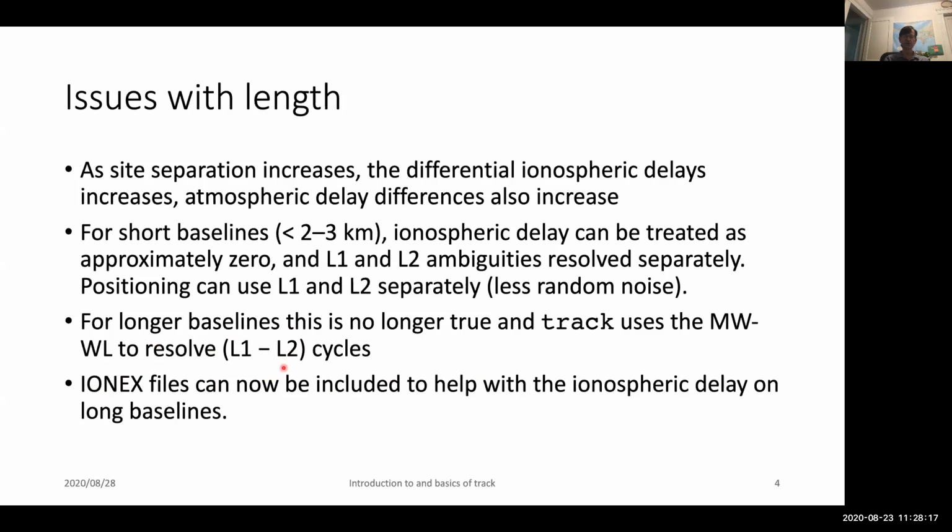In both the long and the short baselines, and particularly in the short baselines, you can resolve ambiguities using the ionospheric-free combination and then set a solution in which you use just L1 and L2 separately or together, or you can switch it around and resolve the L1, L2 ambiguities and then do an LC solution. So there's multiple data types that can be used in the output. So when you're dealing with these short baselines, it's a good idea to try the different combinations just to see how much your results are affected by it.